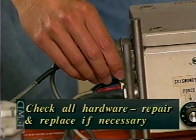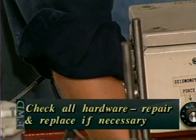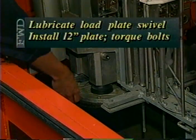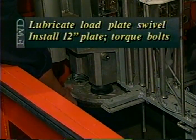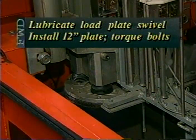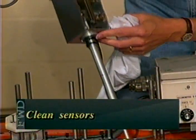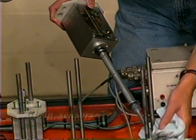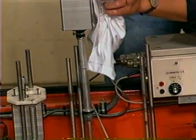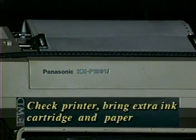First, be sure all connections, fittings, and cables on your FWD are in good repair. If your load plate swivels, lubricate the swivel. Be sure you have a 12-inch diameter load plate installed, and for some types of FWD, torque the bolts to specification. Clean all of the sensors. When you get to the calibration center, you'll need to take the sensors out of their holders.